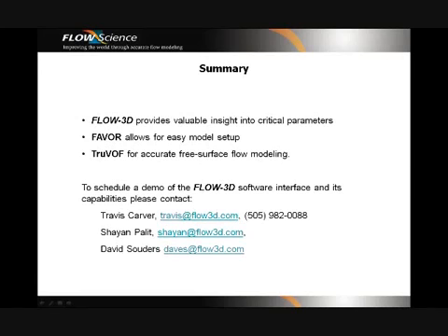Another question is, do you only use air entrainment or density evaluation? Flow3D can run in two modes. You can look at just the air entrained quantity and ignore the bulking effects if the overall volumetric effects are not important. Or if you do consider them important and you need to look at the bulking, you can add the variable density model and look at the volume change of your fluid due to the air.